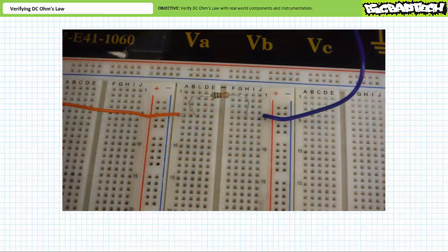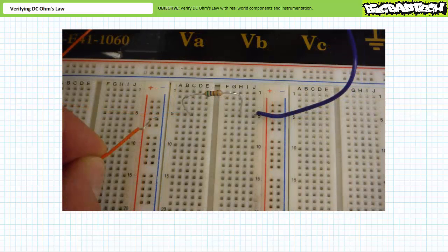Here is a much better way of inserting an ammeter in a circuit. Consider the original unmodified circuit. Power off the power supply. Break the circuit such that the source positive terminal is no longer landed at node 5A through E, but rather dangling out in space. This is an open circuit and no path exists through the resistor.